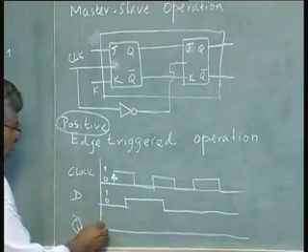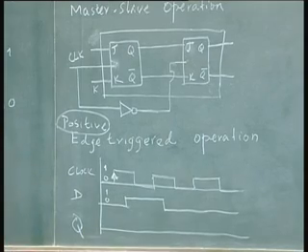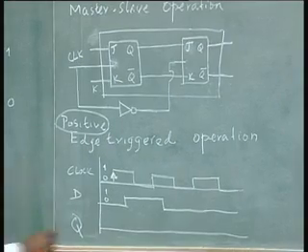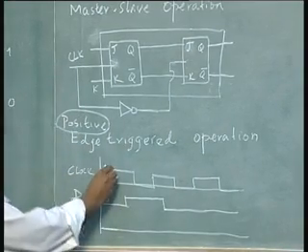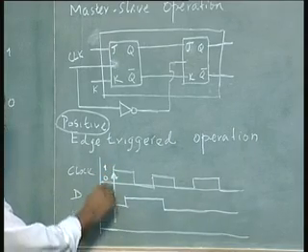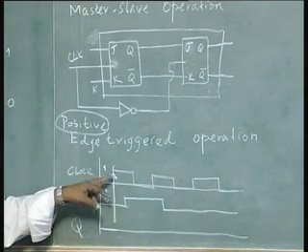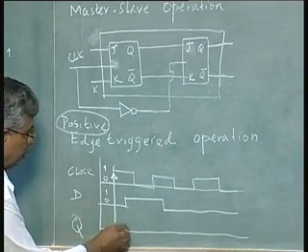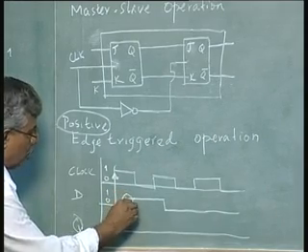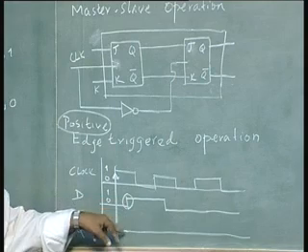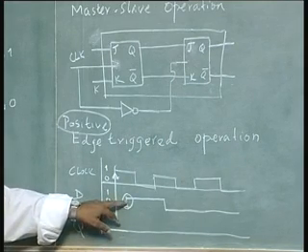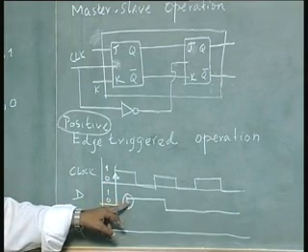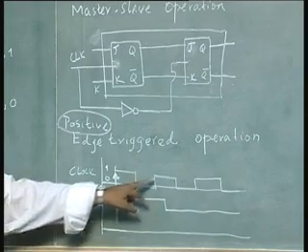So now let us assume the flip flop output was 0. At every transition of the clock, the flip flop circuit will look at the input, which continues to be 0. So nothing happens. Now the D input has changed from 0 to 1 at this point. Will this affect the output? No, it will not, because it is not occurring at the positive edge. The positive edge has already passed before D became 1. This change has to wait for the next positive edge.